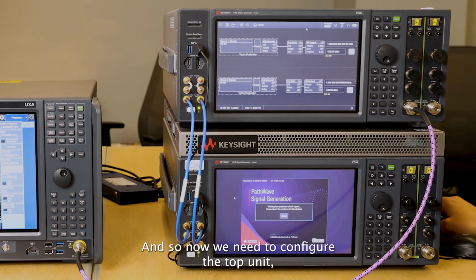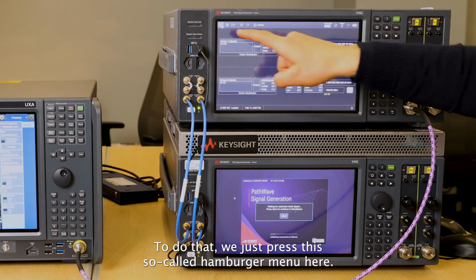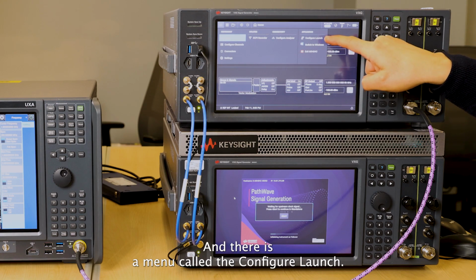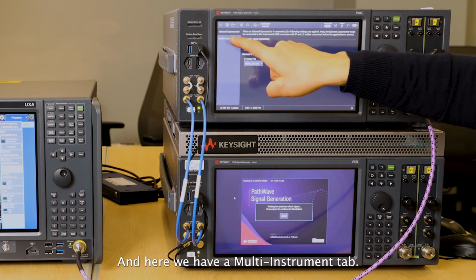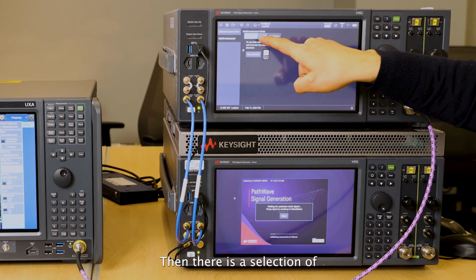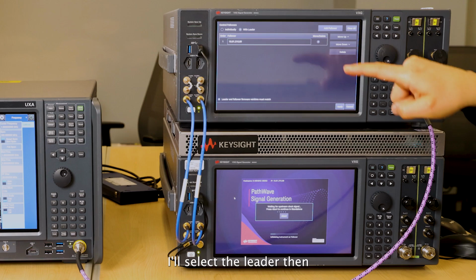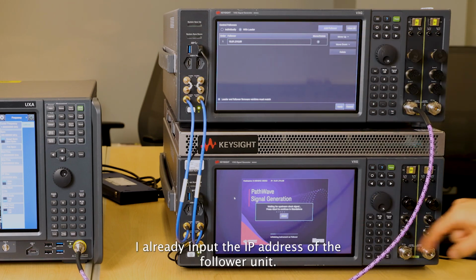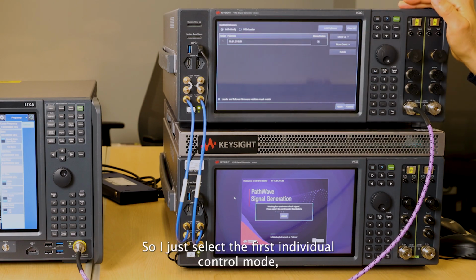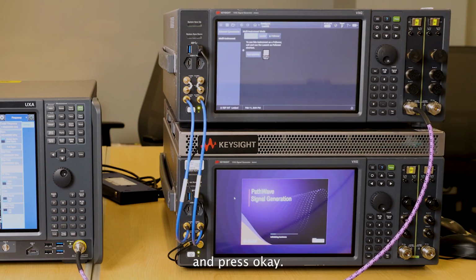Now we need to configure the top unit to become a leader unit. To do that, we just press this so-called hamburger menu here, and there is a menu called configure launch. Here we have a multi-instrument tab. Then there's a selection of instrument mode, standalone mode or leader. I'll select the leader. I already input the IP address of the follower unit. So I just select the first, individual control mode. Then apply and press OK.